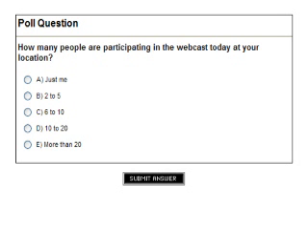In terms of cost, the BMP was built for about $900,000. The annualized cost of that is about $76,000. The annual O&M of that BMP, that includes the backwashing of the filter, the cleaning of the sediments, and the maintenance of the UV system, is about $64,000 per year, for a total annual cost of about $140,000. And that equates to about $104 per acre, or about 34 cents per pound of TSS. That includes both capital and O&M costs on an annualized basis.